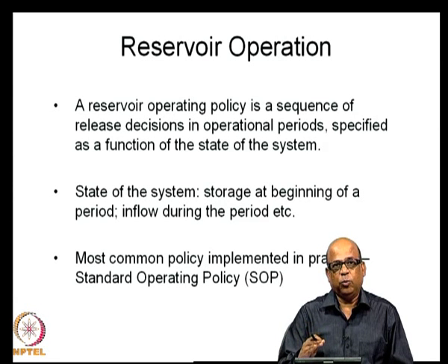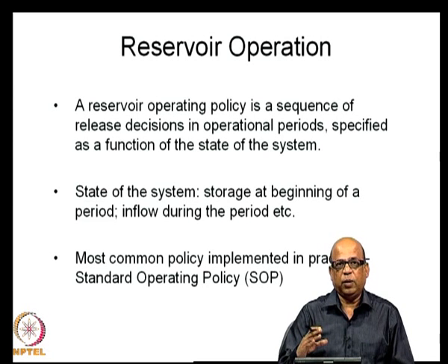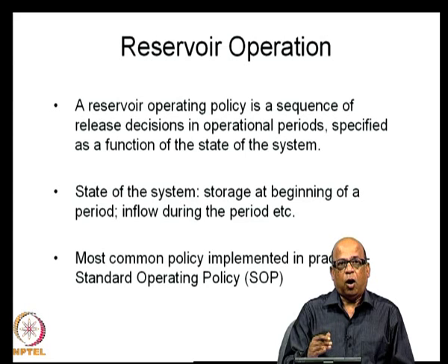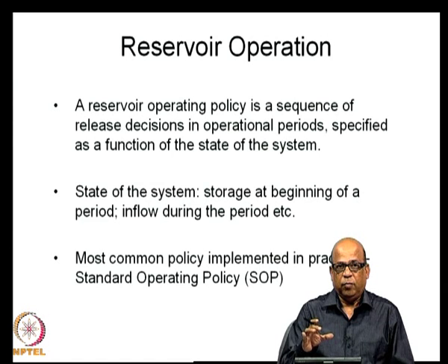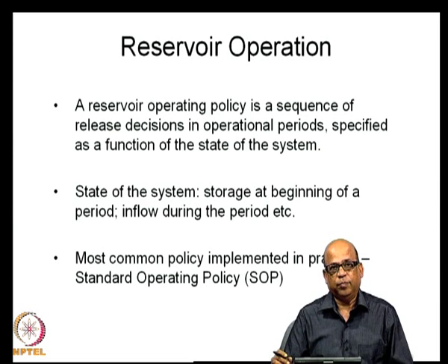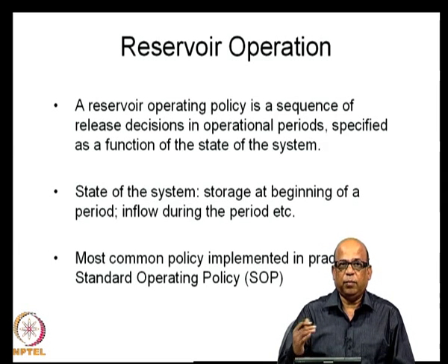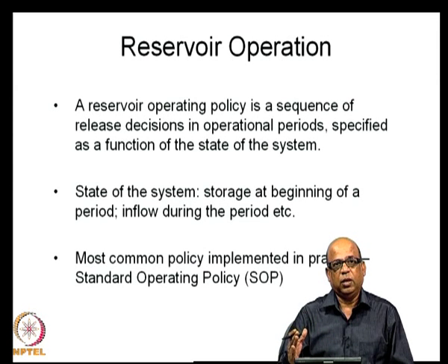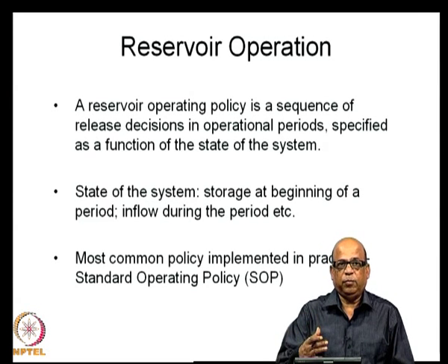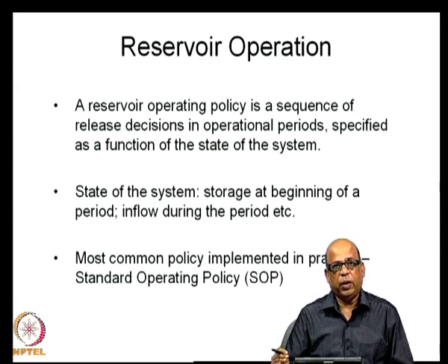In flood time periods, you may operate it on a daily basis, perhaps on an hourly basis. So, you may want to develop your real time operating policies on an hourly basis, or for larger planning purposes, you may operate it for monthly sequences. Typically, we derive the reservoir operating policies on a monthly basis, or sometimes you may want to just examine the seasonal policies. When your interest is in the overall performance of the system, you may talk about seasonal operating policies. That means, in the Kharif season, in the Rabi season, or in the dry season, wet season, what kind of storages need to be maintained and so on.